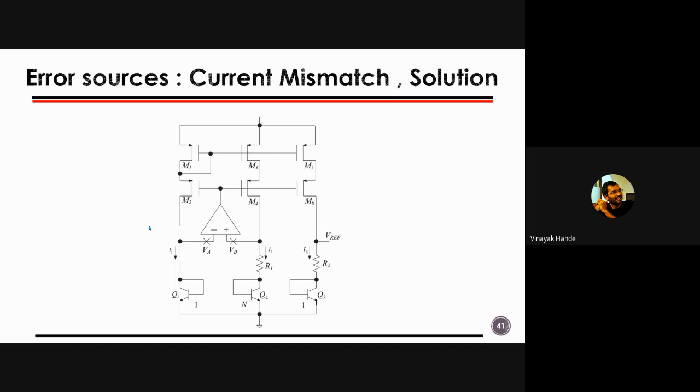Other thing is a similar way. They are putting some cascode. Cascode is also one of the ways you can reduce the offset. It's nothing but a shielding, right? It means the top transistor, by this mechanism, will see the same VGS and VDS. That is also one of the things. But again, we have to increase area. Instead of putting a resistor, we are putting one row of transistors. That's all. Nothing else with this kind of architecture.